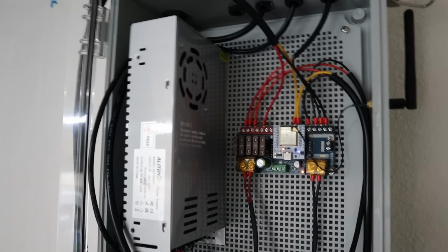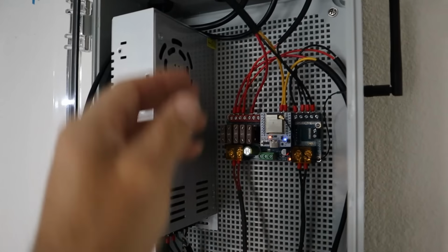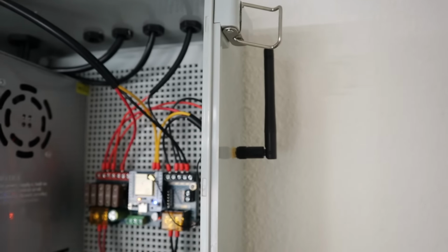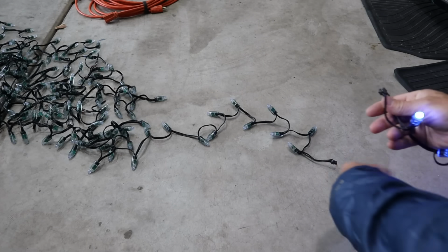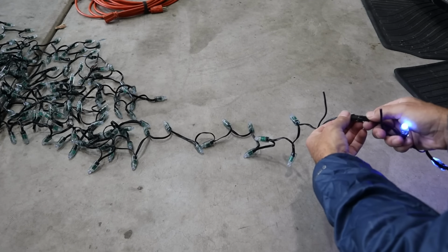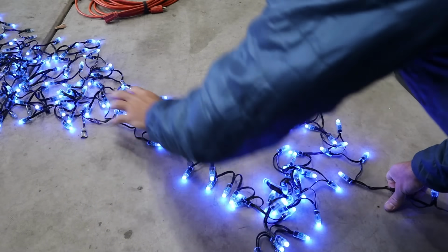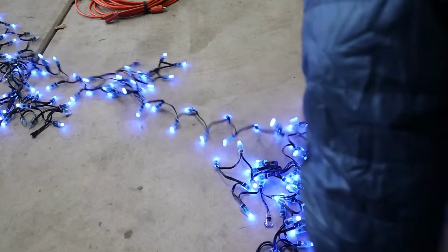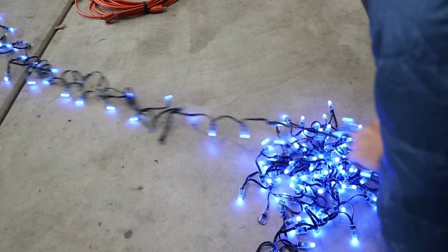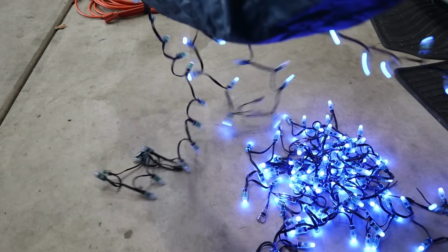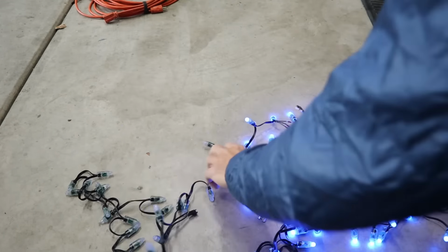So do yourself a favor. Take one of your strands, put some little pigtails off of them, and then hook them into your LED controller and actually make sure they light up, and plug additional strands into that strand to make sure the ones you are about to mount on the house are actually functional before you install them. You're going to save yourself a ton of headache. So test, test, test before you actually install.